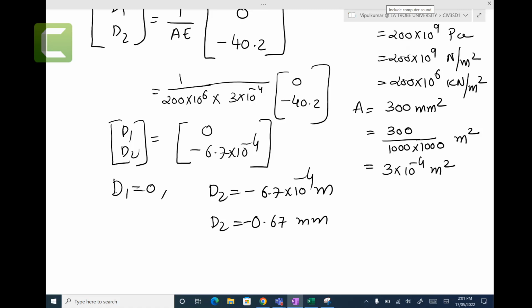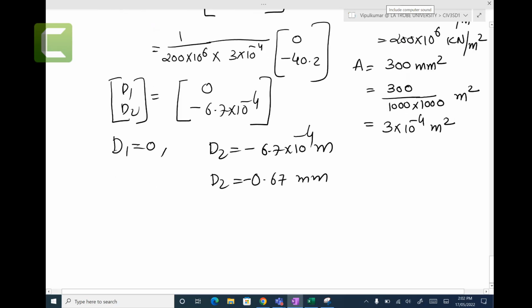If you do this example, what methods can we use? I think we have a force method that we can use, or any method. This is indeterminate, highly indeterminate. You can see there are 6 reaction forces that we need to find. I will show you how to get the reaction forces as well. It's not part of this example, but I can show you once you finish this one, how to find the reaction forces and internal forces, just for the completeness of the methods.